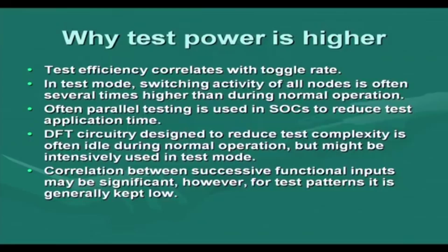Now, leakage power is also a very important part of this whole process, and the problem with leakage power is that part of it will be converted into heat, and for every 10 degree centigrade rise in temperature, this leakage is going to almost double itself. So, that becomes a positive feedback on the system. That will be catastrophic; it may cause a thermal runaway. We will come to those issues later, but in testing mode, power consumption minimization becomes an important issue.